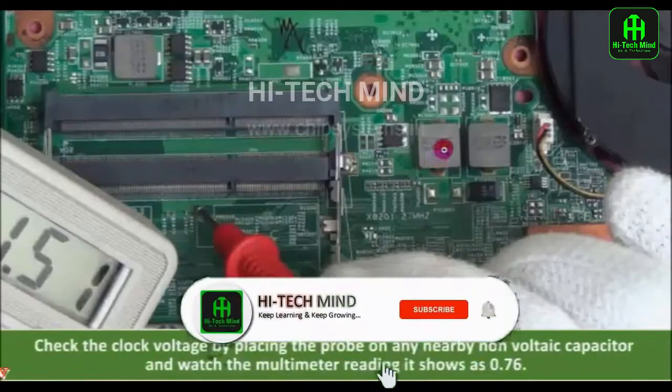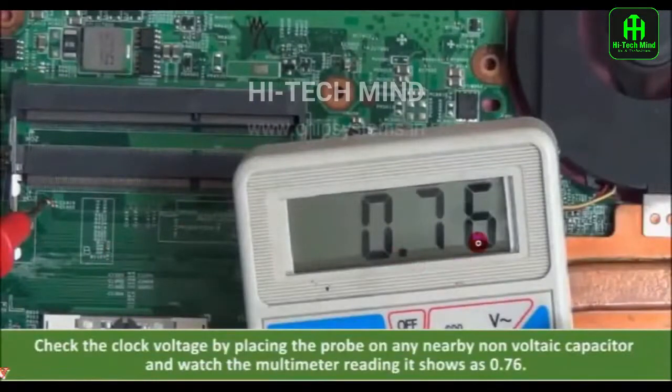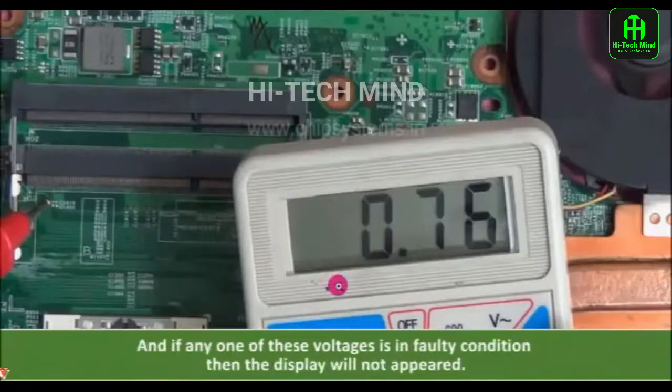Check the clock voltage by placing the probe on any nearby non-polarized capacitor and watch the multimeter. It shows the reading 0.76. Now in the RAM section, both voltages are present. If any one of these voltages does not appear, it is in a faulty condition, and if any one of these voltages is faulty, then the display will not appear.